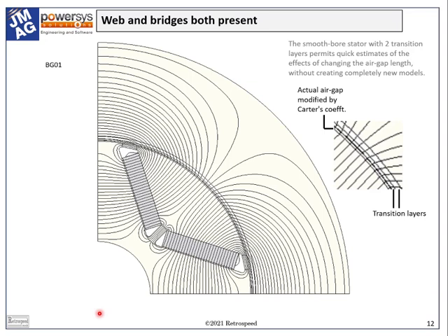In the next video, we will proceed to the calculation of the synchronous inductances which are necessary for performance calculation. But to end this video, I would like to perform a little study which is concerned with the waste of magnet material mentioned earlier due to the back leakage of precious magnet flux in the central web and the 2 bridges on either side of the pole. In slide 10, we estimated the waste at 20% of the magnet material.